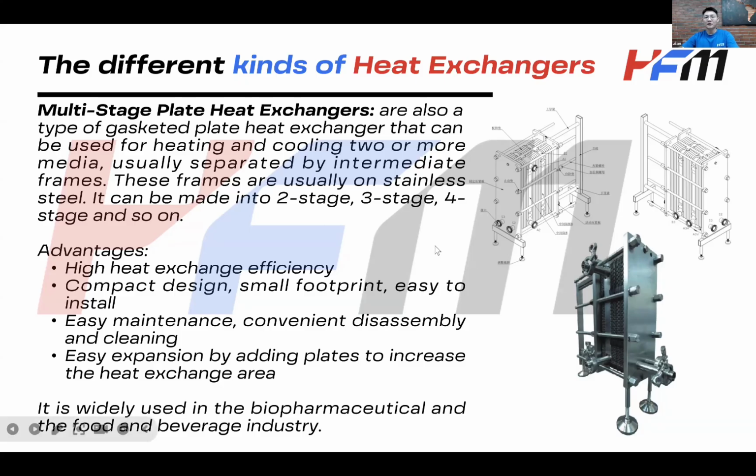And it can be used for heating and cooling two or more fluids, usually separated by an intermediate frame. So the frame is a special one. And the material for the frame is usually stainless steel, and it can be made into 2, 3, 4, or more stages. It depends on the design and requirements.